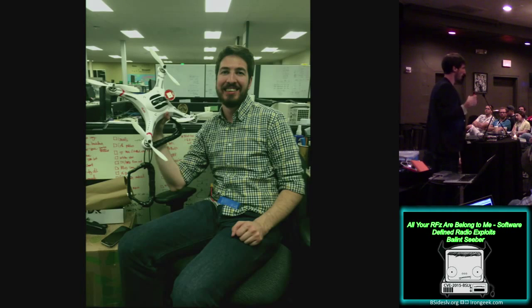So this drone had an old version of the firmware that had a flyaway problem, and it probably had flown for miles and miles and miles out of the control of the original users, ran out of battery, and fallen to the ground. Now, drones are supposed to have a fail-safe feature that enables them to land safely when they reach a low battery condition. We got in the car, raced around trying to find the thing, found it, hooked it up to the laptop, downloaded their software, checked the settings, and they had set the low voltage battery fail-safe feature to 0.1 volts. That's not exactly going to work.